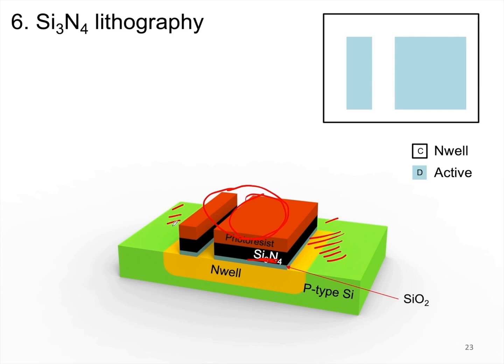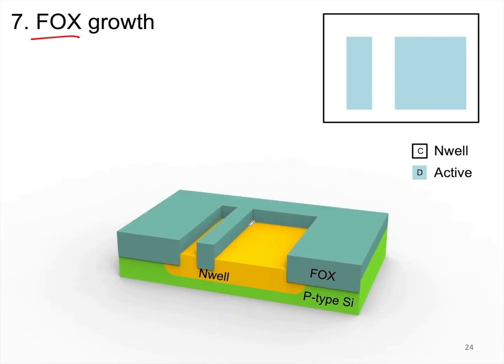device. The property of this layer is dark, so the parts with patterns have metal, while the parts without patterns are empty. When exposed to light, the resist in the parts without patterns is removed, while the resist protected by the mask is retained. What comes next is the etching of poly. As there's resist protection above the gate, this poly area isn't etched away, while the poly in other parts is completely etched away. This area has resist.